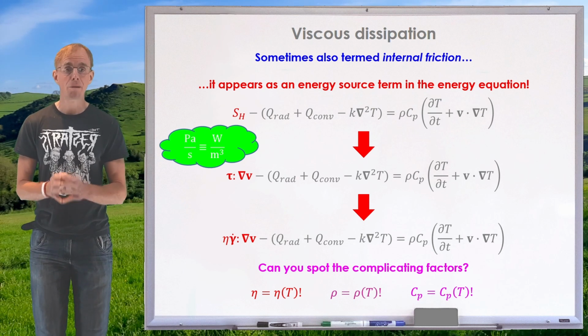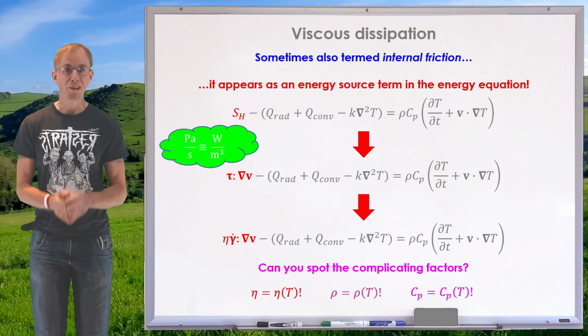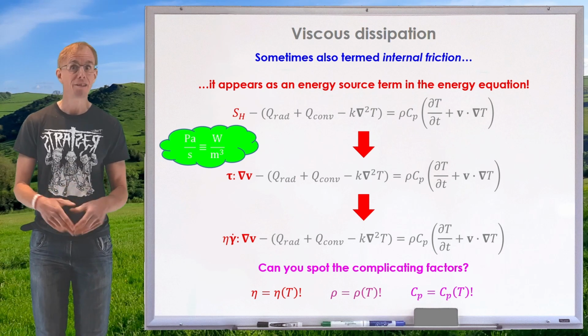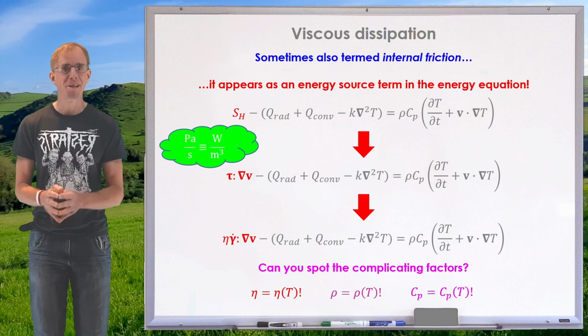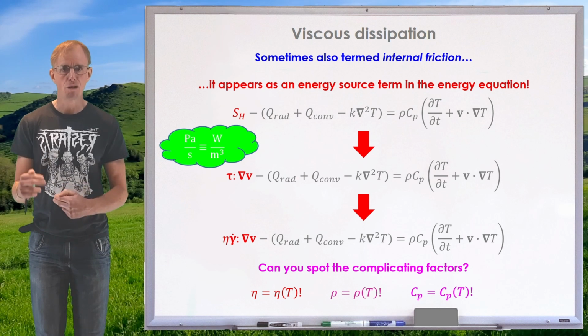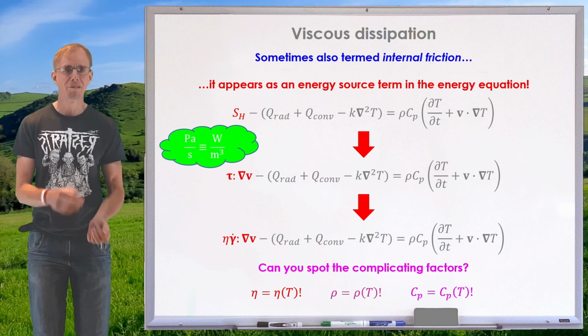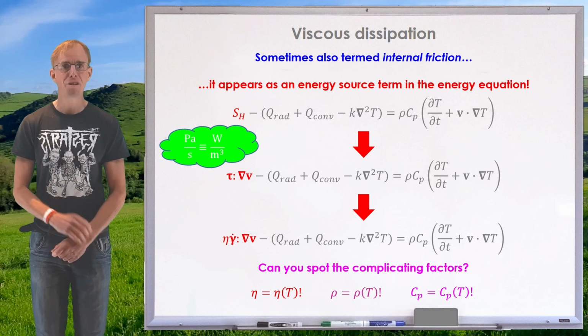If you're doing capillary rheometry of viscous liquids, what are you doing? You are flowing a highly viscous liquid, typically, especially if you're dealing with a polymer melt, through very narrow geometries at incredibly high shear rate. Why are you doing this? You're doing it to measure a pressure drop so that you can measure the viscosity of a material. We're assuming, in doing that, it's isothermal.